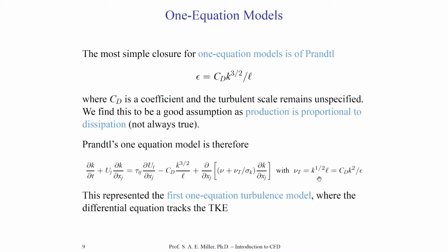So when we add up the number of equations for turbulence closure, we're really only adding the partial differential equations, not algebraic equations. Then we have, of course, sigma k, which is another constant. So really, there's only a couple constants and one real variable that we don't know, plus L. But of course, we have another equation for L. So we really have one PDE and one algebraic equation here, if I'm counting them correctly.